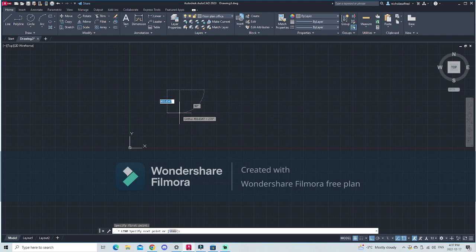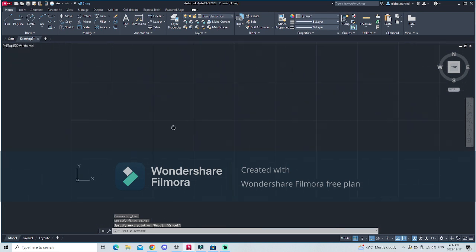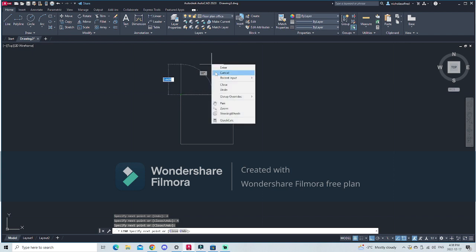We're going to go down, say 16 meters squared, so we're going to go 4 by 4. I'm going to zoom in here actually, just to make it a little easier to read. So we're going to click line, click anywhere on the screen, go down, and then on your keyboard, type 4, enter to confirm that. Go to the right, 4, enter, up, 4, enter. And then, as you can see here, the little green indicates that we're entering the end of a line, so click that. Then right click, click cancel.